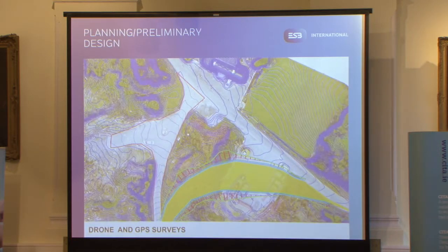So we just have an example here. Colin spoke to you about a drone survey he did on one of our upcoming wind farm projects in Grousemount in Kerry. And we're widening a lane for access into the wind farm. And Colin did a drone survey which produced a detailed aerial image and contours of the area, which allowed us to overlay our design on top of it, finalise our design, and work out the relevant quantities. You just see the design overlaid there.